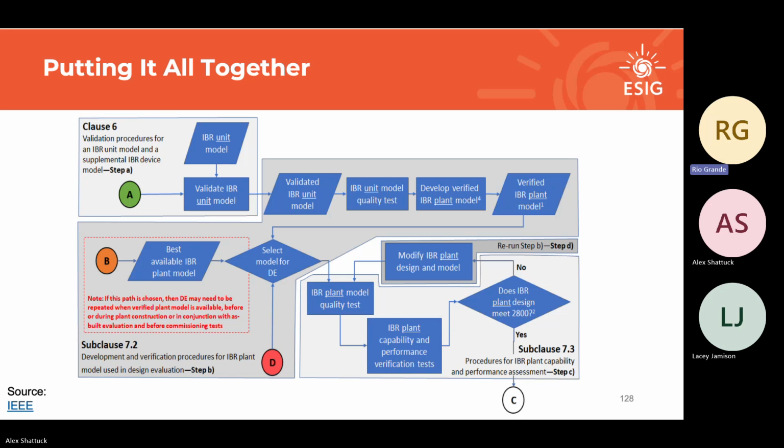So it's very similar. And we pulled a lot from ERCOT's model quality process, the model quality assessment in the dynamic working group manual. So if anyone has experience using that DWG manual, those tests in there, like the high voltage ride-through, the low voltage ride-through, they don't look like real faults, right? It's not a representation of a system fault.